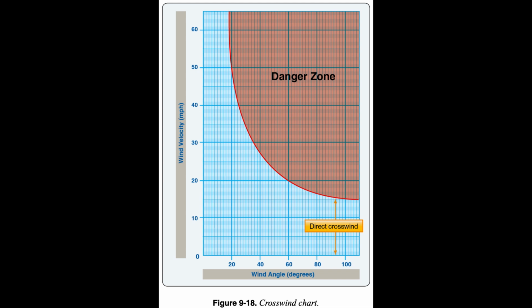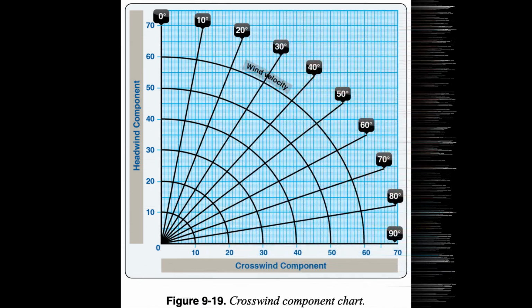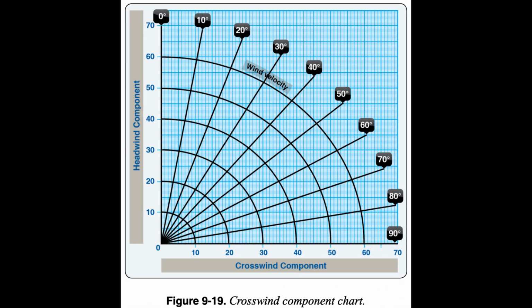End of page 9-18. Before an airplane is type certificated by the Federal Aviation Administration, FAA, it is flight tested to ensure it meets certain requirements. Among these is the demonstration of being satisfactorily controllable with no exceptional degree of skill or alertness on the part of the pilot in 90 degrees crosswinds up to a velocity equal to 0.2 VSO. This means a wind speed of 2/10 of the airplane's stalling speed with power off and in landing configuration. The demonstrated crosswind velocity is included on a placard in airplanes certificated after May 3, 1962.